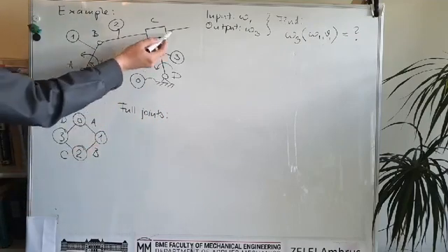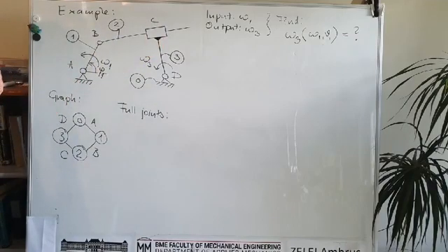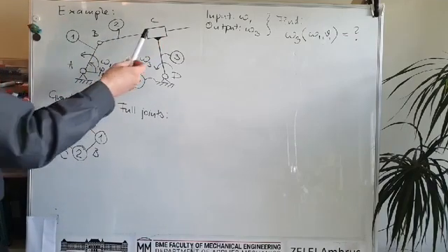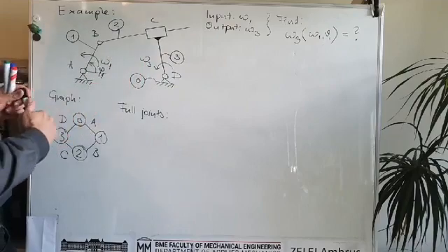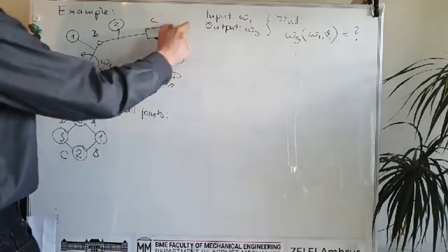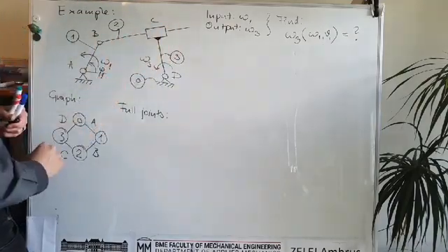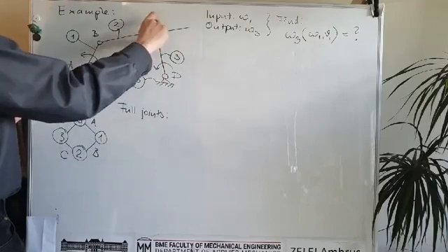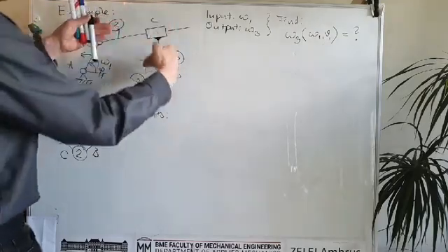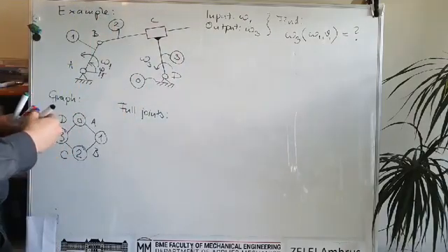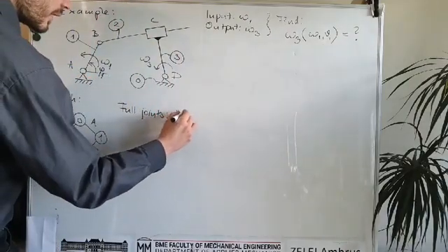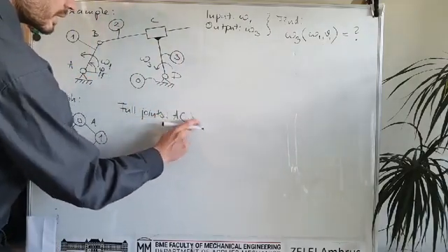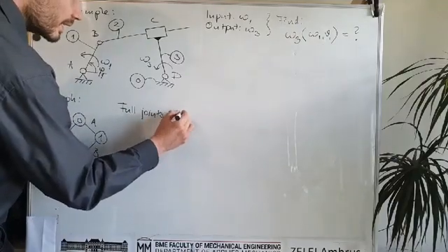And here we also have a full joint because it allows only 1 degree of freedom. It can only slide in this direction and no other type of motion. So it cannot rotate and it cannot move perpendicularly. So basically all of them are full joints. Sorry, the order is A, B, C, D.